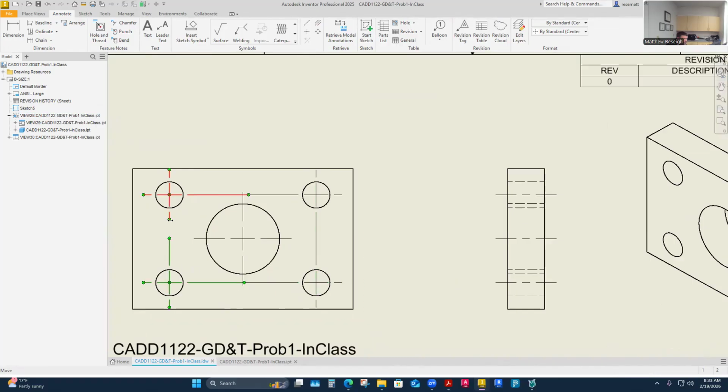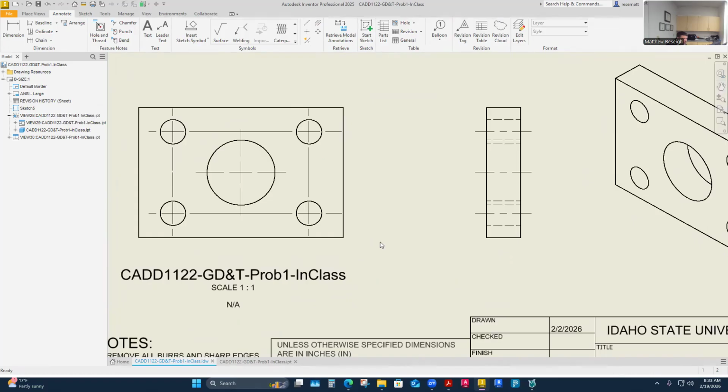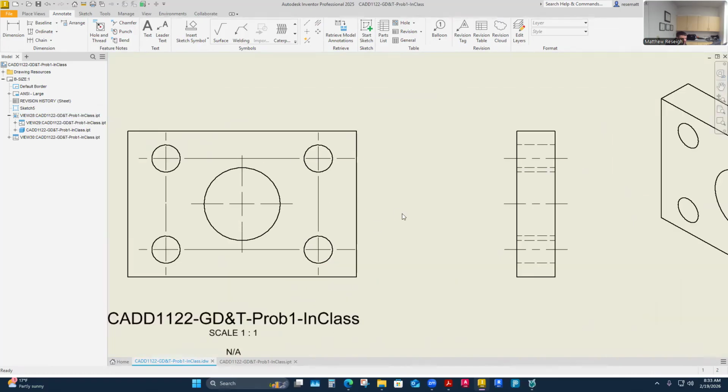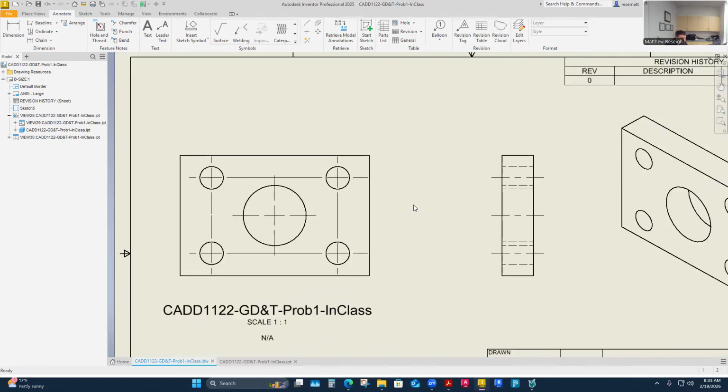We're going to run this. We could definitely set up some dimension styles and help us do this. Three decimal. I'm just going to run it pretty manual, almost like I'm dimensioning with CAD in some ways. Although sometimes CAD's dimension styles are, I mean, they're just as easy to build here too. But they'll have a two-dimension decimal style. But I can drop one dimension, then I can copy the properties, or I can drop them all and then change one and copy all the properties. So I might just do it manual like that.